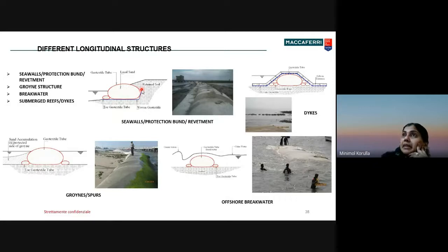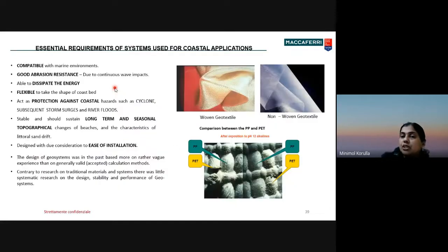Geotextile is a polymeric product, and using that, we can make a big tube or a big sack and fill soil inside it. Geotextile bags can be small, with dimensions like 1 meter by say 0.75 meter. Whereas geotextile tubes can be 20 meter or 30 meter or 50 meter. Such tubes, if you fill them with the same local material, dredged sand from the same place, can act as a big retaining wall or a protection for the riverbank slope or the coastal slope.